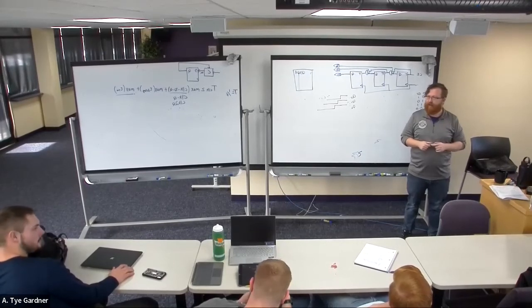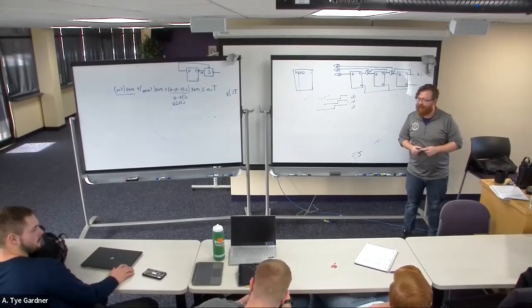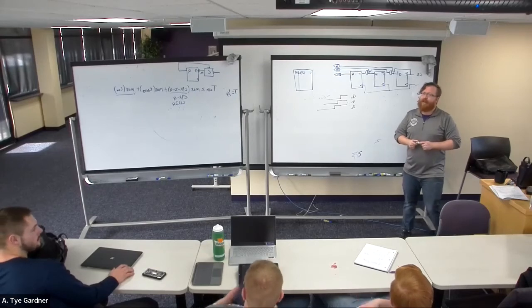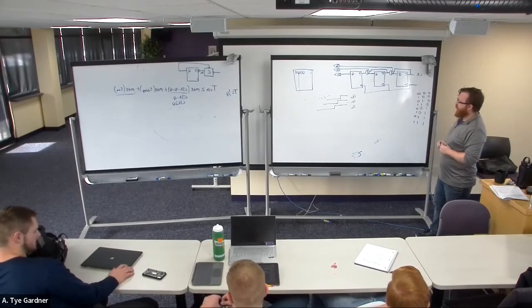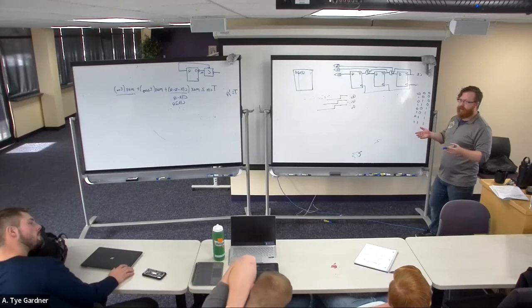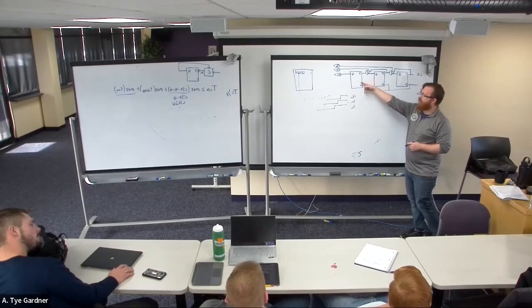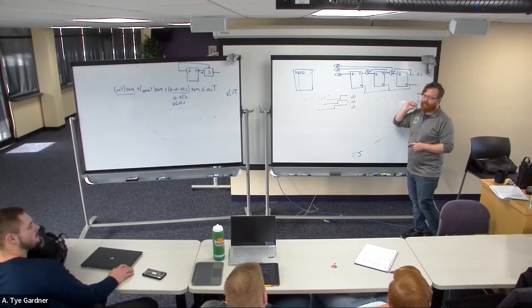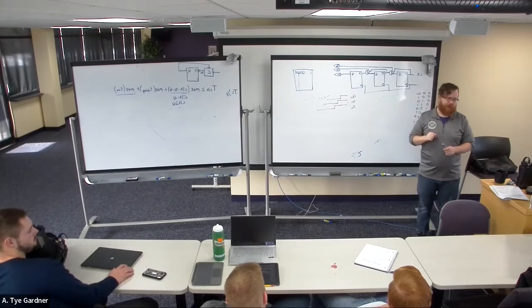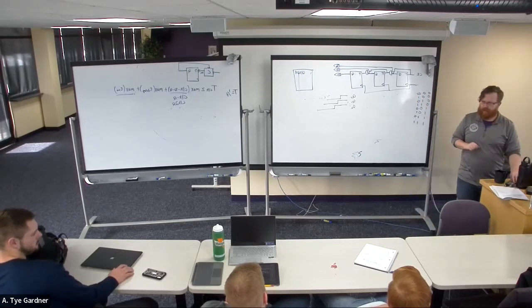So fix that: you don't go faster than you're allowed. No, you can do a lot of things to fix it that we'll talk about architecturally, which is if we need to go faster, we build a more complicated circuit. We'll build circuits that don't depend on the previous delay. That's what we would do. But it does add complexity.